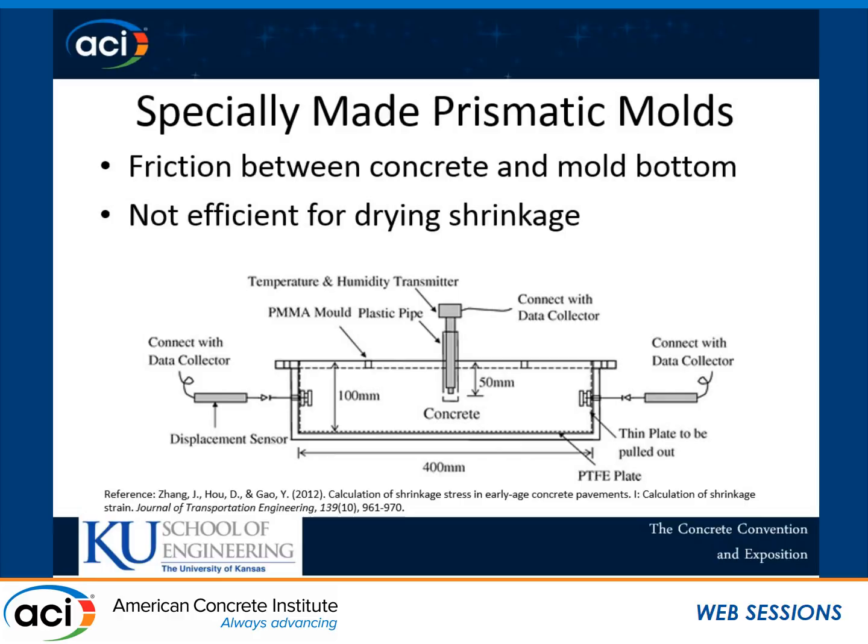The drawback of this test method is that the friction between the concrete specimen and the bottom of the mold can be significant, and it can be a restraint that limits the deformation. And also, for drying shrinkage measurements, this setup can be inefficient because the specimen needs to stay in the mold.